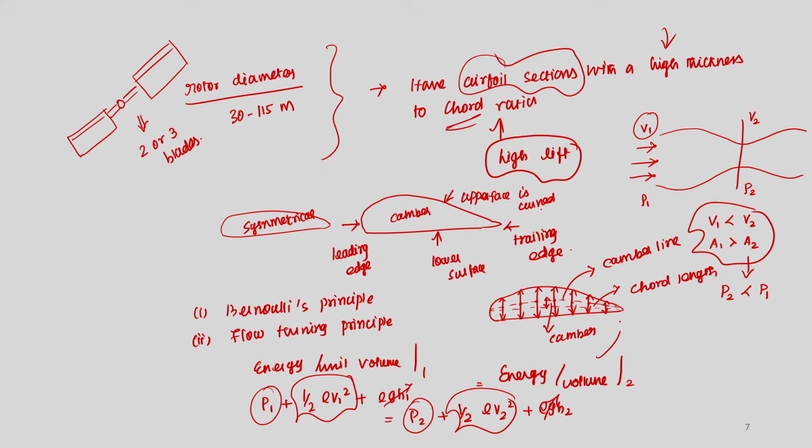So, how do I relate this to the airfoil section? The air is coming in with the free stream velocity. It has to see the stagnation point and take the curved shape of the airfoil section, and some of them go to the lower surface as well. The upper surface takes longer time because it has to travel the larger surface.